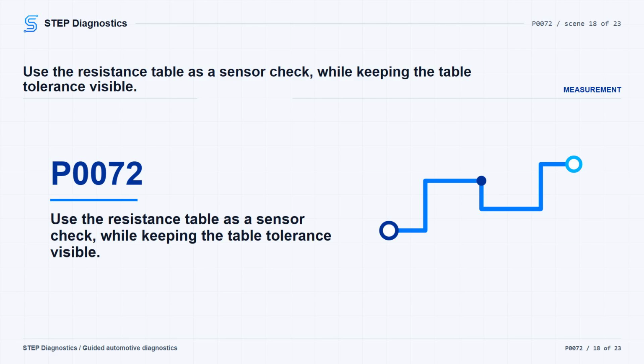If a temperature table is available, move the switch to adjust, connect an ohmmeter to the test leads, and dial the tool to a resistance value in the table. Connect both leads to the temperature sensor harness connector with the ignition on. Then monitor the scan data for the proper reading while varying resistance and watching the temperature sensor signal temperature or voltage. If the actual temperature can be acquired or reasonably estimated, measure resistance across the sensor terminals and compare it to the table. The actual resistance can vary +/-10% from the values in the table.